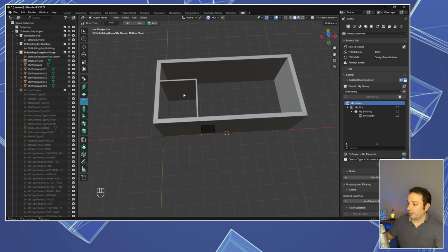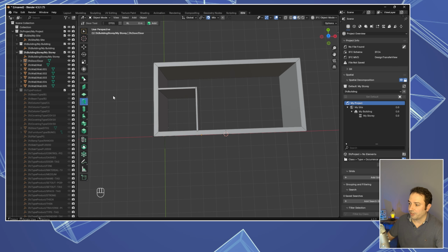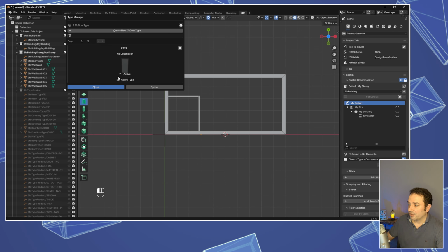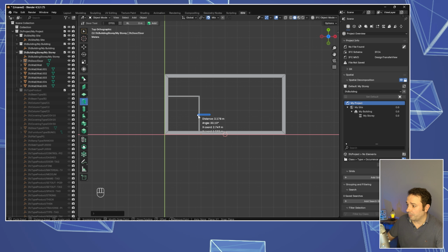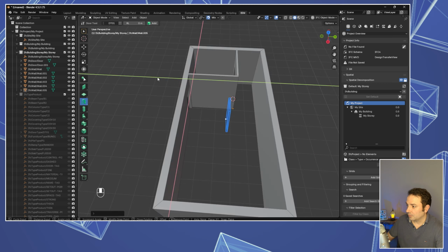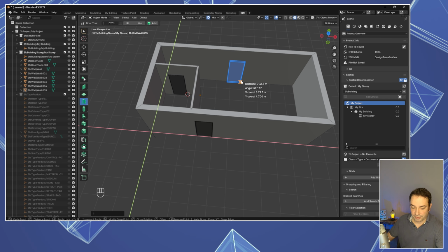And if you want to create a new door for the interior part of the house, of course, we need to follow the same steps. So let's go to door, select this door, and press add. And for instance, in my case, I'm gonna locate it. Let's put it on this wall. So now you can see that we have also a door inside, and let's press ESC.